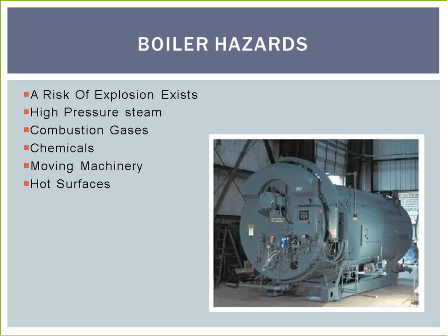Number 2 is thermal shock. This is a condition where low water causes the heating surfaces to become overheated and then cooler water is added. The water then flashes to steam, which expands 1,600 times its volume as water and causes the explosion because there is not enough room for the steam to expand.